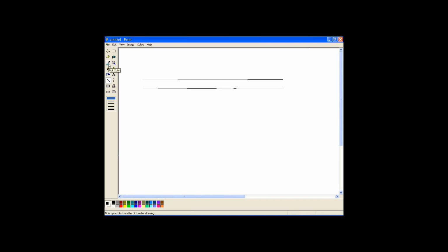And what happens is when you enter in the set point of a fast ramp rate or a 0 time interval, the system's going to go at 100% throttle all the way up until it hits that proportional band. So in this case, 77. So it's going to go 100% throttle until it hits the proportional band, and then once it hits it, it's going to start backing off, to give you something like that.